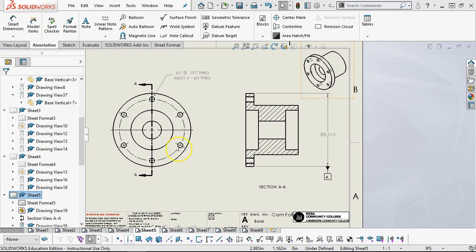All right, so let's see if I can remember that off the top of my head. The way I kind of work these is 0.1 millimeters would be about 4 thousandths. 0.01 millimeters would be about 4/10. And so we're just under 0.1 millimeters, so about 3/10 of a thousandth to 0. That seems pretty tight. We'd have to do the conversion on that one, but at least it gives me a ballpark on the shaft. And then the OD tolerance minus 0.011.